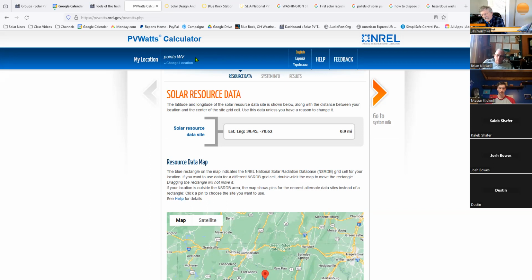So eventually, if you do this, you're going to come to a number that you like with a certain product. So for instance, if you're doing microinverters, maybe you say, let's just always derate at 94%. SolarEdge, let's do 90%. And that seems to work out, unless there's something unusual. Okay.